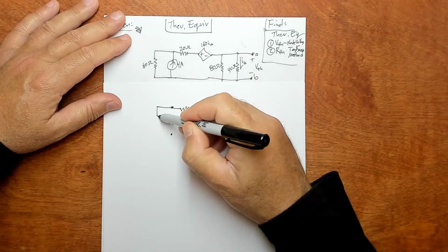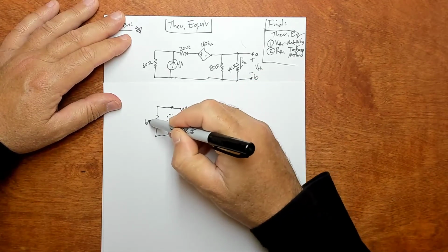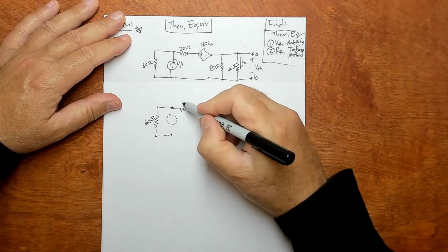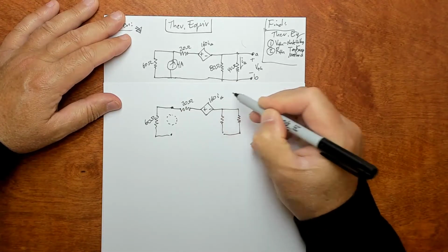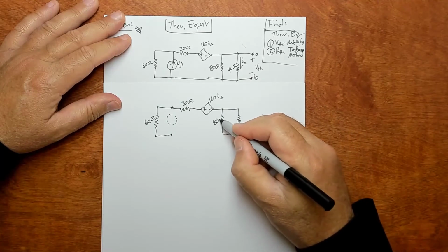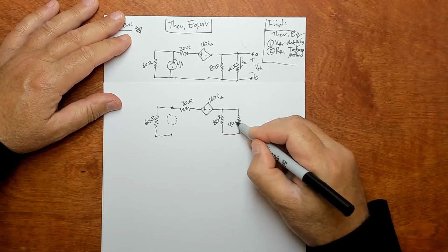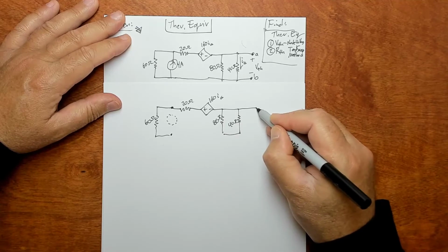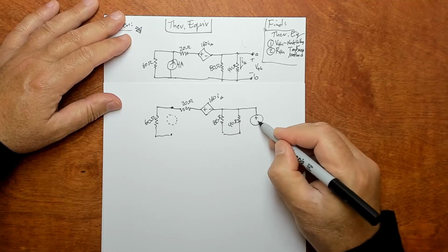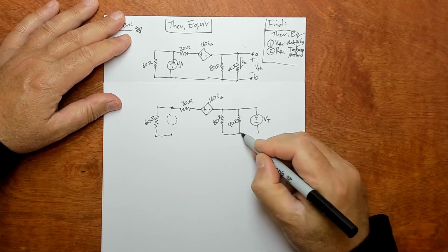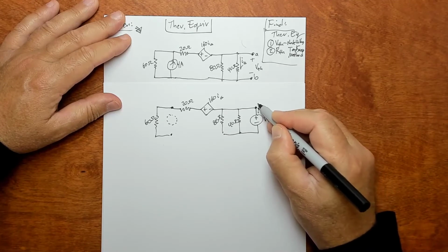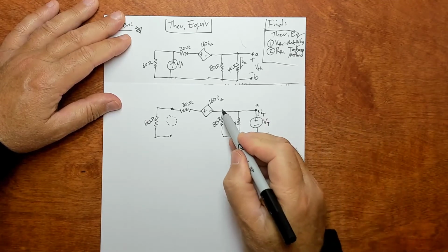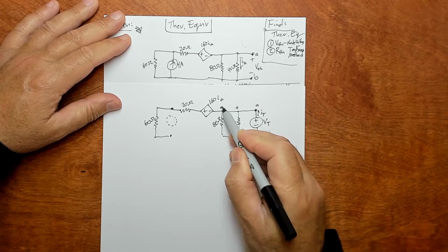And this guy stays there. So the 60 ohm stays there, the 20 ohm stays there, this 160 I delta stays there, the 80 stays there, the 40. And then we hook up a test source, V sub t, because we're using test source method, and we're going to have I sub t going into this node A. And node A is all the way across the top here on these 2 guys.